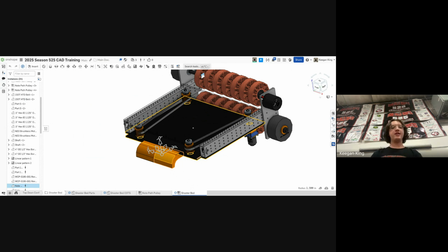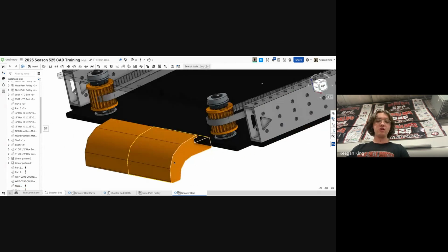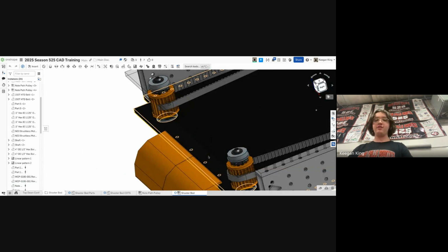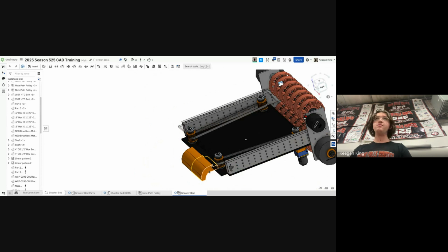So what I actually had to do is I went to that part in our CAD folder and changed the tessellation quality, and then I made a new version and pushed that version forward to get a part with coarse tessellation quality so that it could be used for this document that we're going to be working on. So it's saved to the part itself.